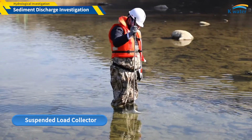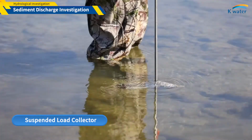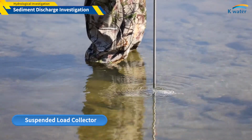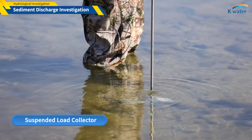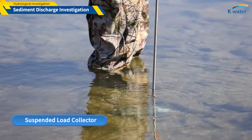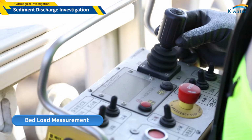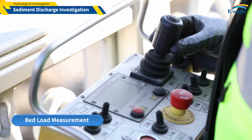The point integral suspended load collector has an electrically operated valve. Therefore, it can collect the suspended load at any point on the vertical sideline or only from a portion of the measurement section. The bed load measurement is a method of unloading equipment on the riverbed and collecting soil for a period of time.